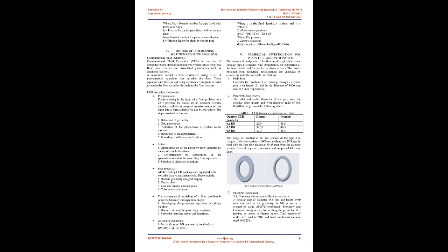3. Pre and post experimental data reduction. 3.1 Reynolds number, Re. 3.2 Wall surface temperature, TW. 3.3 Bulk mean temperature, TBM. 3.4 Nusselt number. 3.5 Friction factor. 3.6 Thermal performance factor, η. These are the calculations that need to be performed before conducting the experiment.